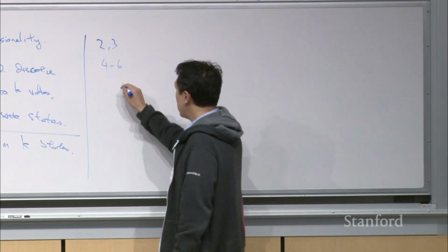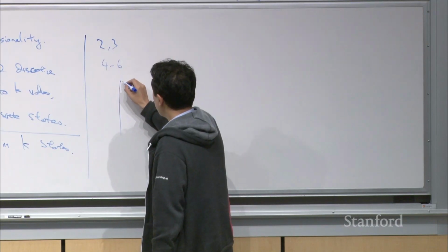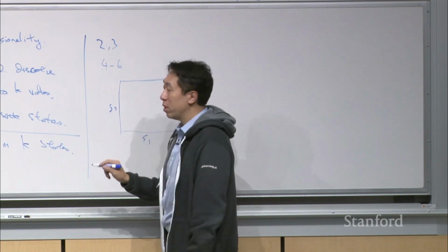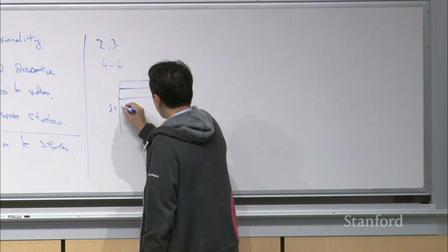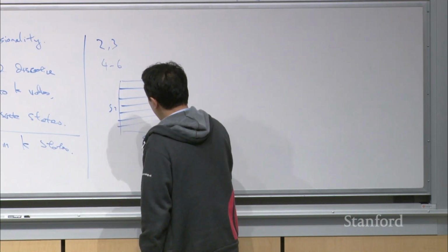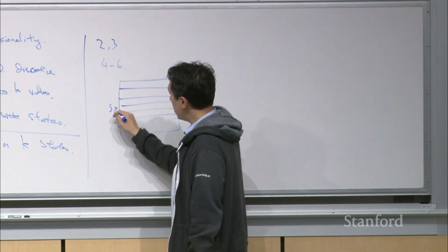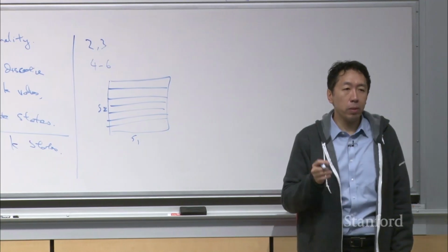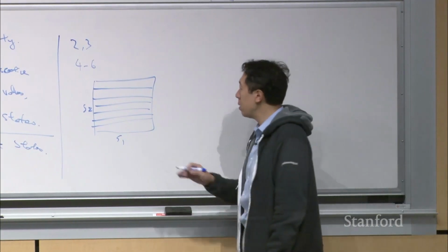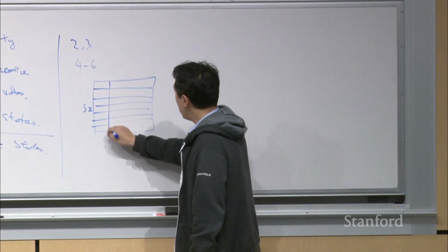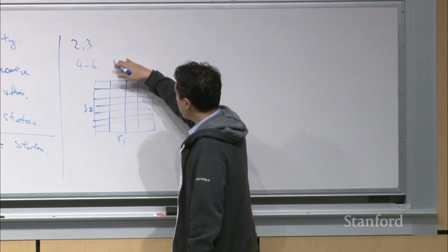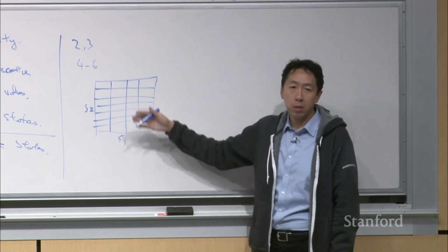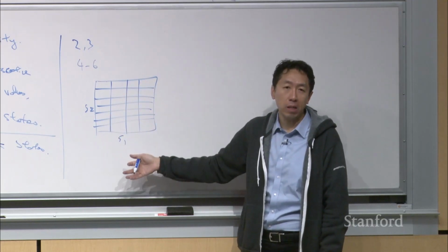One of the tricks you want to use as you approach the 4 to 6-dimensional range is to choose your discretization more carefully. For example, if the value of the performance is really sensitive to the state S2 and less sensitive to the state S1, then in this range, people end up designing unequal discretizations where you might discretize S2 much more finely than S1.